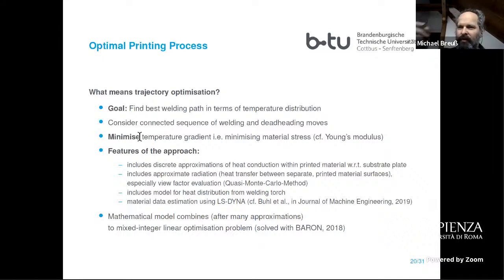So every drop of metal that you print heats the other drops of metal that you print, and vice versa. So everything is connected, and this is via this radiation. And this is what you have to simulate for basically every step in this printing process, the radiation between the material that is printed.